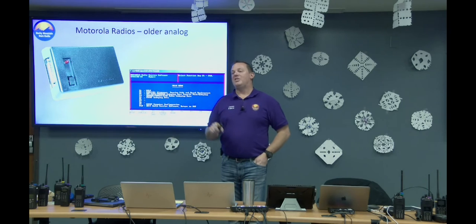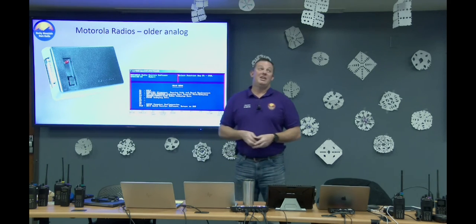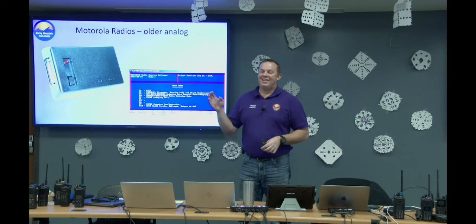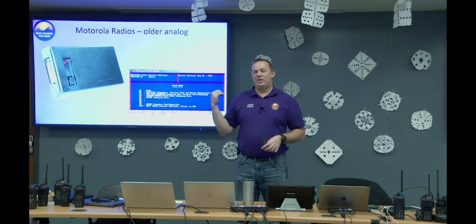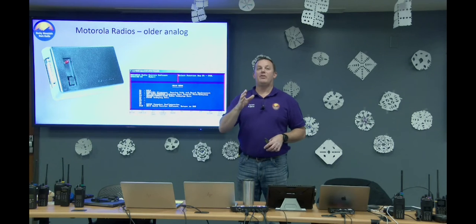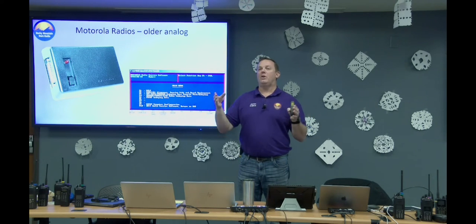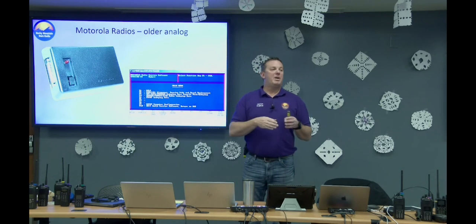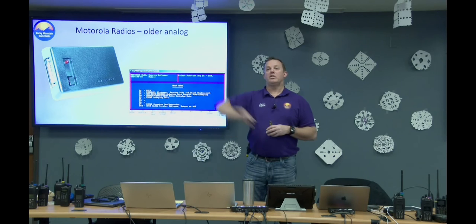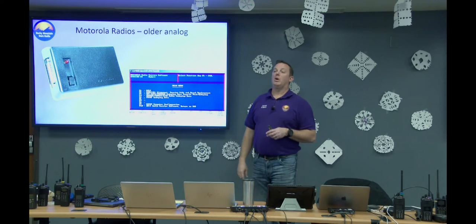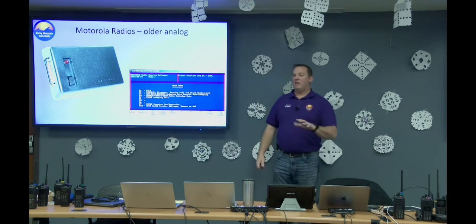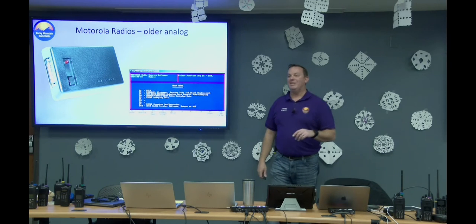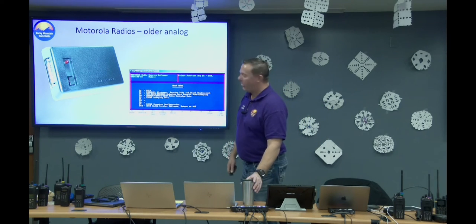Yeah, so that's the other thing you have to be careful of when you operate them out of band. The reason is that a lot of the old GM300 era radios have a lookup table in their EEPROM, and they know what to adjust the PA for based on that lookup table. And when you're out of band, the lookup table is false, so it just defaults to full bore, which can be okay. It can also burn out your PA depending on the usage there.